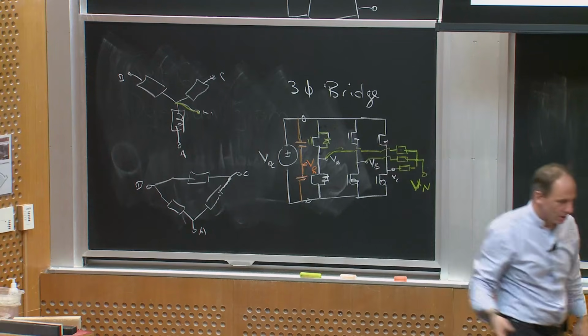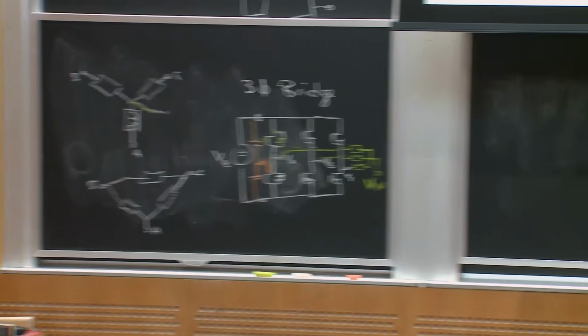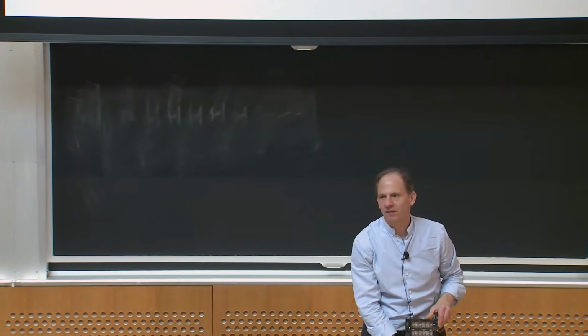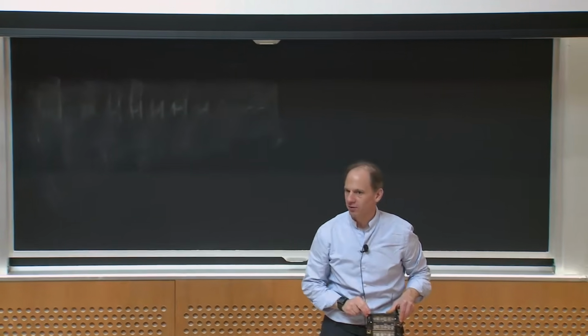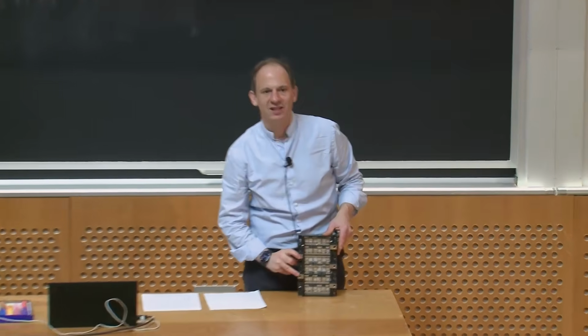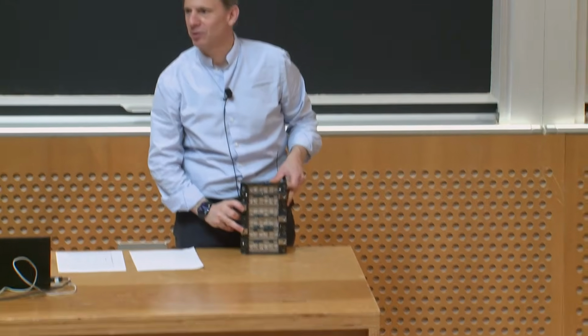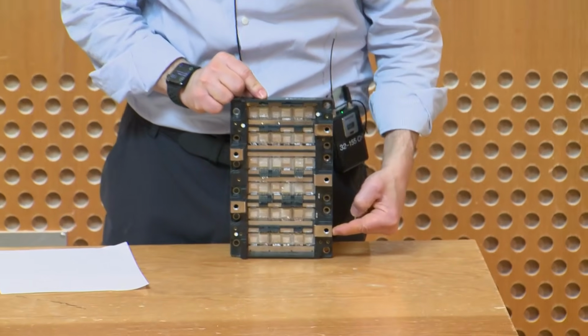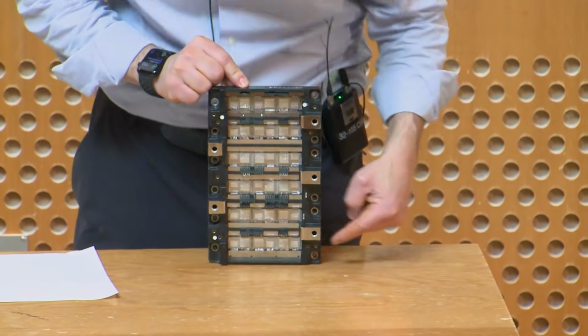Just to illustrate this, I'll show you this guy here. This is actually an inverter out of an older model Prius. You'll see the 2 in here, that's the DC bus coming in. That's where the capacitors and everything else would hook up and go back to the battery. And then there's phase A, phase B, phase C outputs.